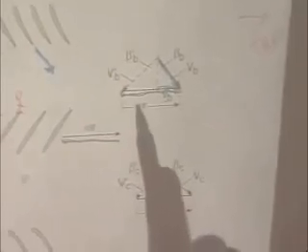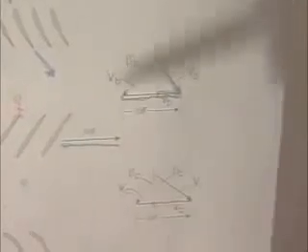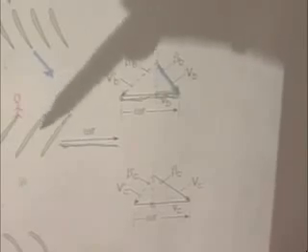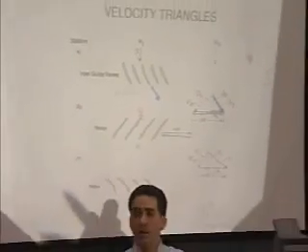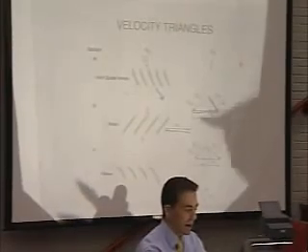So yeah, unclear. My apologies. If you are in this reference frame and you want to transform it to the reference frame of someone sitting on these blades, you need to take account of the speed of this reference frame with respect to that one. So this reference frame is moving past this one in this direction at omega r, or from this perspective, this one's moving past this one in this direction. That was a lot of thises in that statement. Let me finish the vector addition here, and then we'll talk about it.